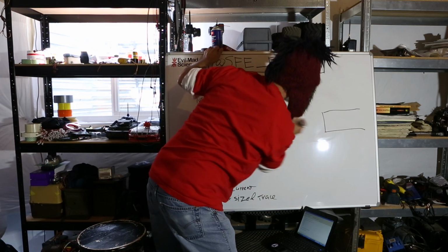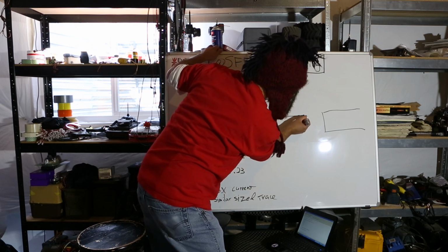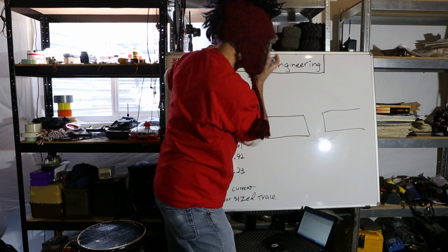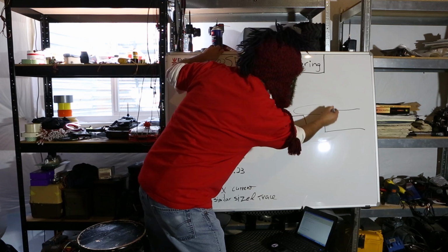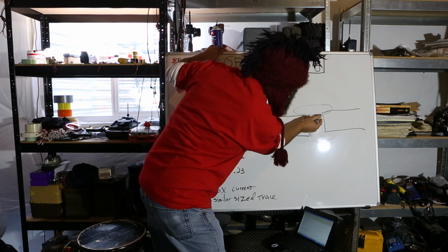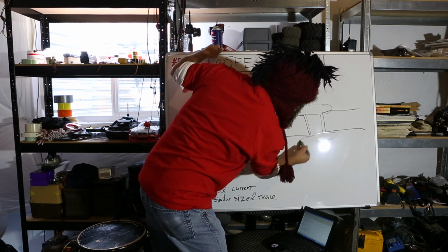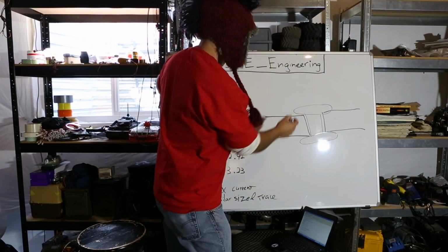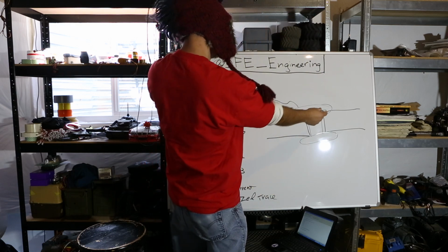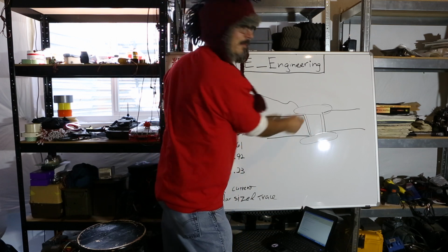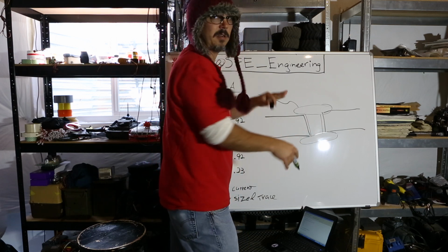If this is a cross-section of a PCB, and that's our drill, a via is going to have a bunch of metal here, it's going to have the inside coated there, and it's going to have a bunch of metal there. And if you've got like a 10 mil trace going to that via, this is not going to be the weak link in your signal, right?